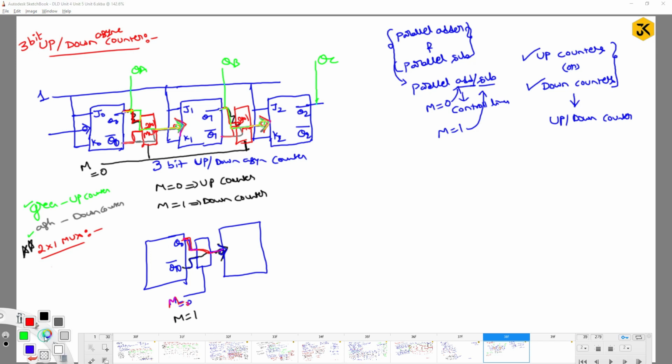So instead of having the mux, can we go for a simple basic combinational circuit? Yes. If you remember how the mux works, it has two lines as input, it produces one line output, and we have one select line. This will be I0, this will be I1, this will be output Y. Y here means some kind of clock signal.